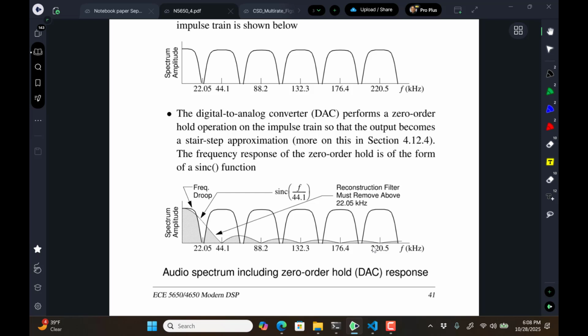And although none of that is audible, it still would be driving the electronics and possibly could produce some distortions or overloading. It's best to just clean this up and get this squashed way down. And squashing down is just a crude sounding term, but it just says so many dB down. You never send it to 0, but you can push it down 10, 20, some additional numbers of dB. And to this day, you still have a sync correction filter, and you have a homework problem on that, on this set number 5 too, where you would possibly peak up to get rid of that little bit of roll-off there.